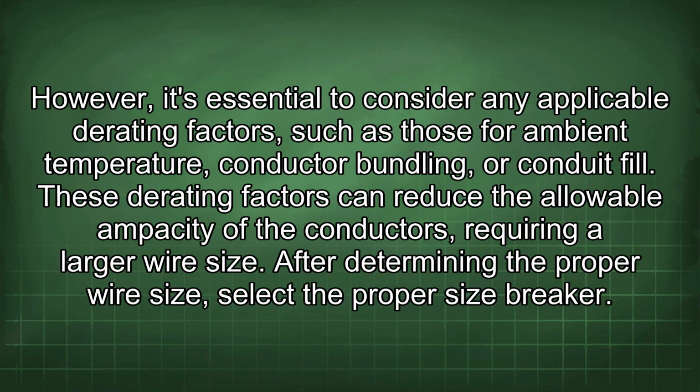However, it's essential to consider any applicable derating factors, such as those for ambient temperature, conductor bundling, or conduit fill. These derating factors can reduce the allowable ampacity of the conductors, requiring a larger wire size. After determining the proper wire size, select the proper size breaker.